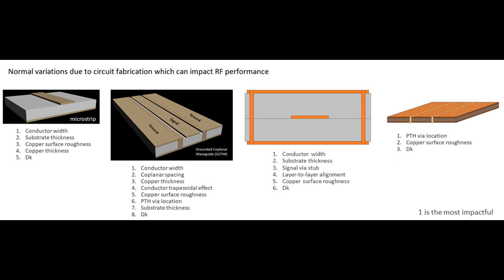And in this case, for SIW, that's a very big deal at millimeter wave frequencies, but at lower frequencies, microwave and below, that's really not too much of an issue. So I've seen a lot of SIW circuits at lower frequencies, and then at millimeter wave I've seen a few, but not a lot. And it's mostly because of that number one issue of the via hole location tolerance.